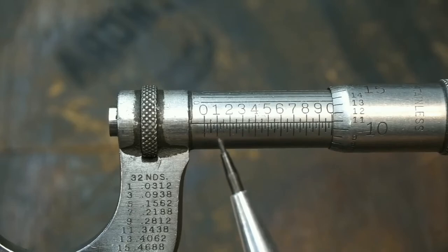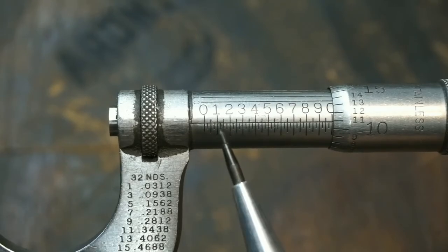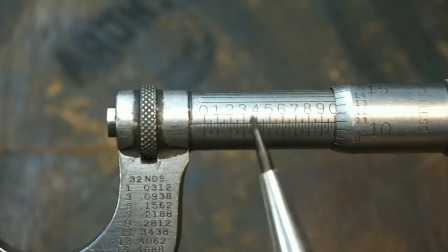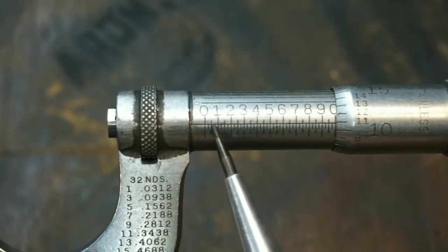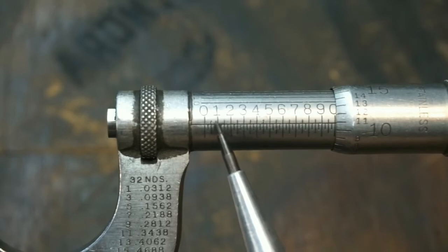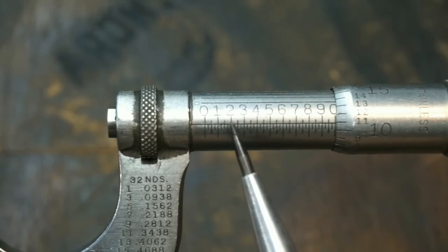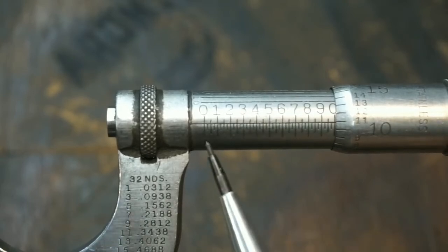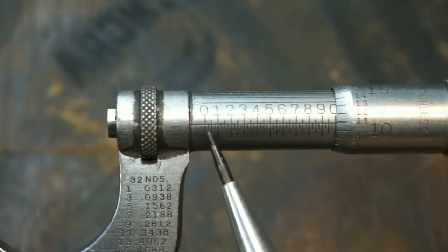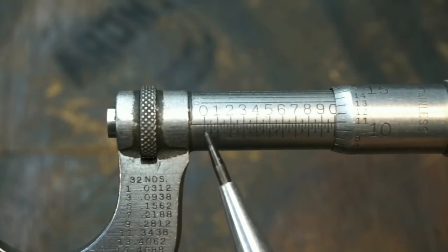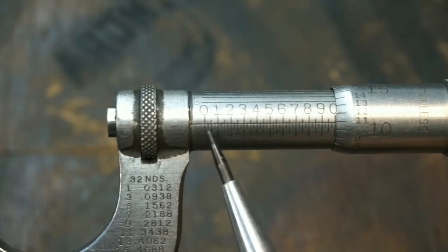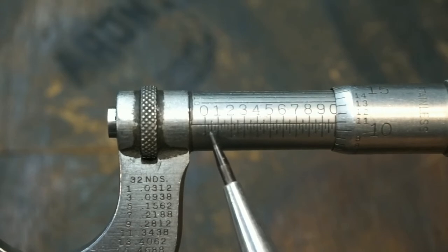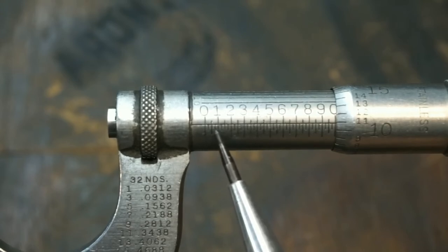All right. Also on the top line, let me see if we can get you in a little bit closer. No, that's it. You also have a line in the middle there, so that's 50. So that'd be 50 thousandths, 100, 150, 200, and so forth. There's 250, 3. Alrighty. On the bottom of that line, I know it's a little bit harder to see there, but each one of those lines is going to represent 25 thousandths of an inch. So starting with your 0, first line will be 25 thousandths, the second line will be 50, third line will be 75, and then the fourth is going to be exactly 100 thousandths.